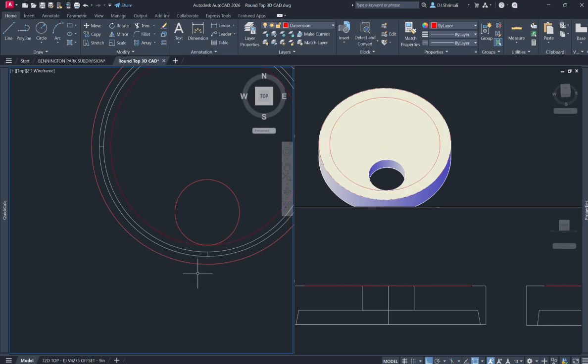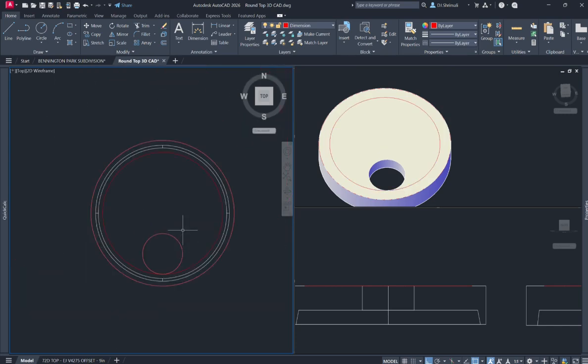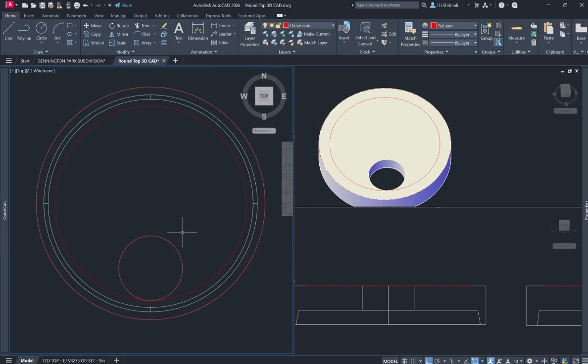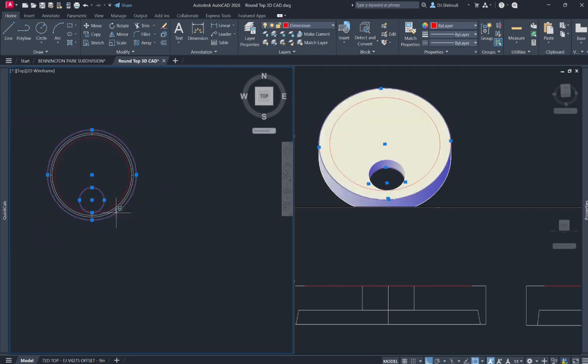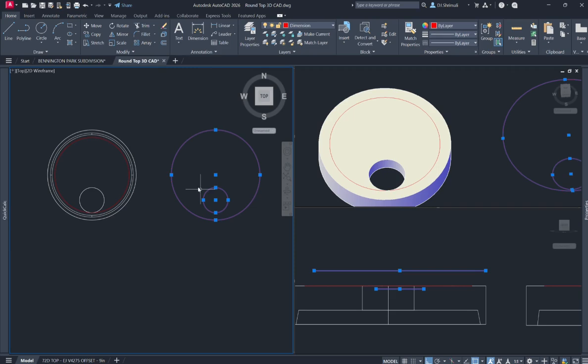Okay, so for that I created the 2D of the top view. As you can see, the red lines are the 2D of the top, and in that I will create the reinforcement lines. We can create the reinforcement in 3D as well using the cylinder command, but that takes a little bit more time. So I prefer doing it in 2D and 3D. The 3D I do is basically just to calculate the weight of the top and to find out the centroid, so that I can place the lifters along with that, and we'll dig deeper as we go through the top.